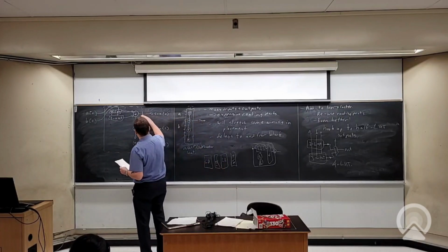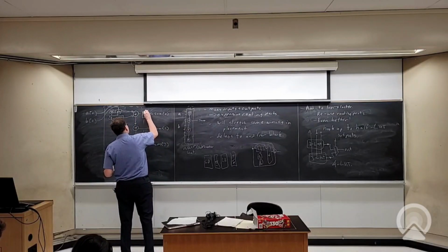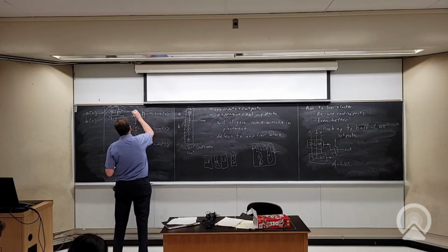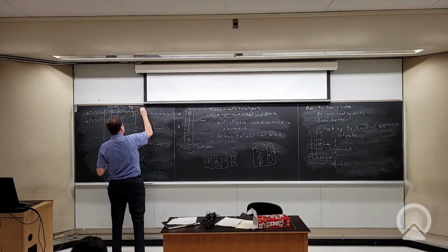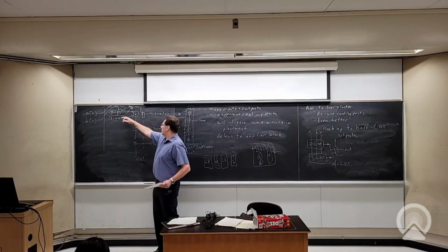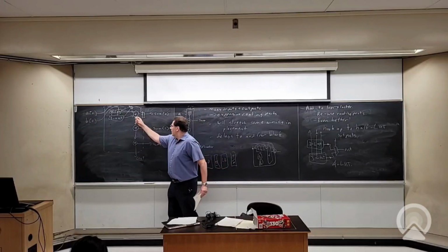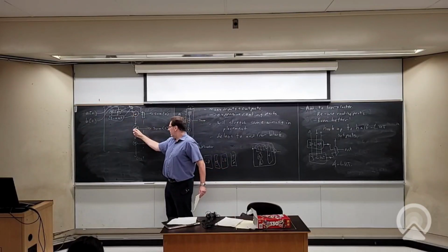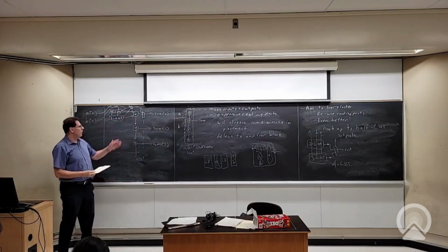And I would also have a mux here, right? So maybe I'll draw that. There would be a mux that takes the final LUT output, right? These 2 things would go to a mux that's controlled by the last input. Okay, so I can still do a regular LUT function. I just basically bypass the adder. Or I can do an addition using hardened logic for the adds and for the carry chain. And I can still do some LUT logic before I get into the adders.